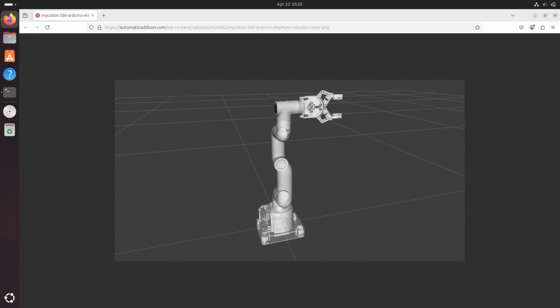Both file types represent the robotic arm, but XACRO offers more flexibility and organization. Before a ROS tool or component can use the information in a XACRO file, it must first be processed or translated into a URDF file. This step allows for the dynamic generation of robot descriptions based on the specific configurations defined in the XACRO file.